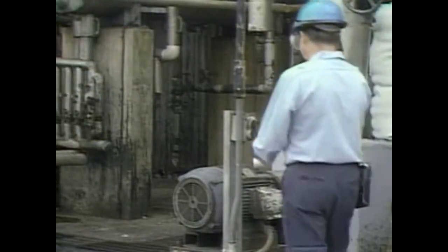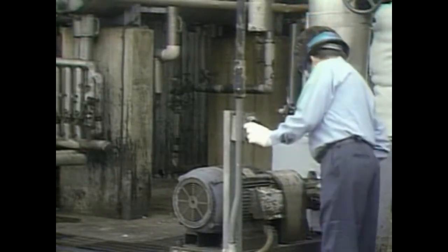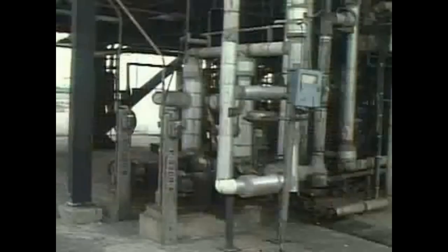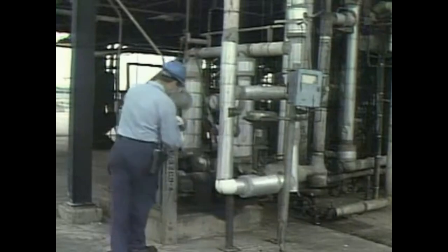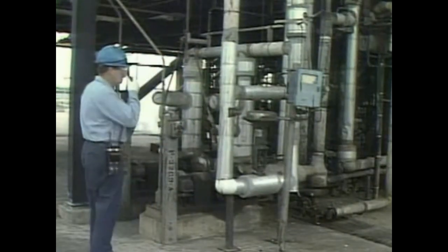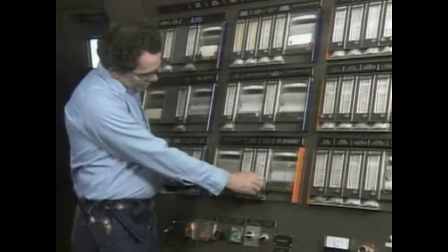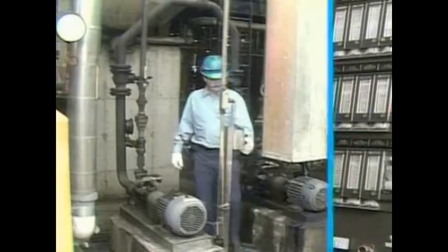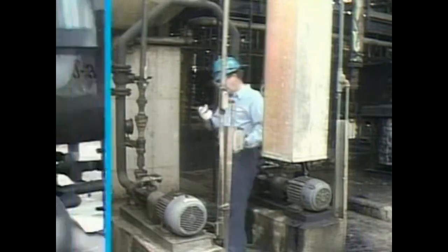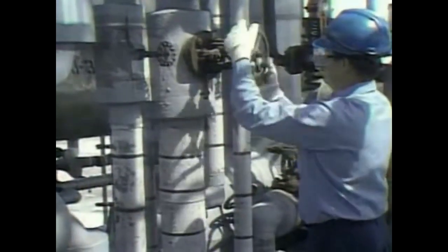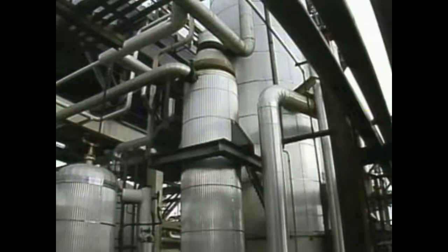This often involves shutting down equipment that could pose hazards if it were allowed to continue running. Backup equipment may need to be left in operation to stabilize conditions. Once conditions have been stabilized, an emergency shutdown will likely involve stopping the flow of feed mixture to the column, stopping the takeoff of overhead product and bottoms product, and possibly shutting off the reflux system and the vacuum system. Procedures such as draining the column and the reboiler are avoided unless they're needed to maintain safe conditions.